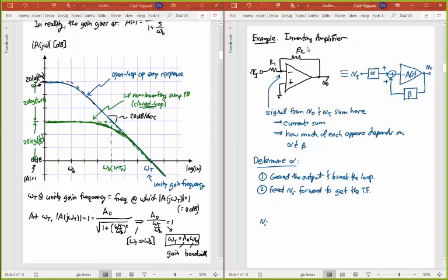If this is VI, I look at my circuit up above. VI, of course, goes into resistor R1. R1 goes into V minus, right? And this is where the op-amp is. Let's draw a dotted op-amp. This is where it was. That was the minus terminal of the op-amp. This was the plus terminal. But the real circuit that I'm interested in is not the op-amp. I'm interested in the resistors going across this. And so I have this resistor here that was R2, and I'm now grounding this. This is the circuit that now determines my feed-forward transfer function, alpha.